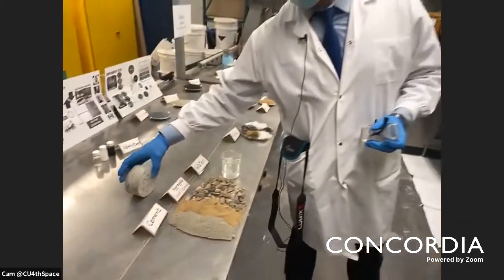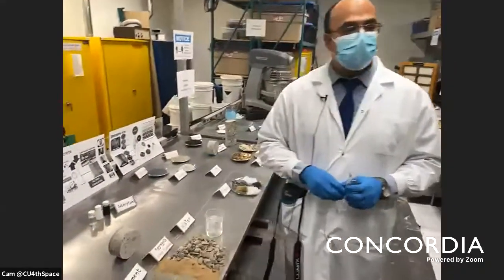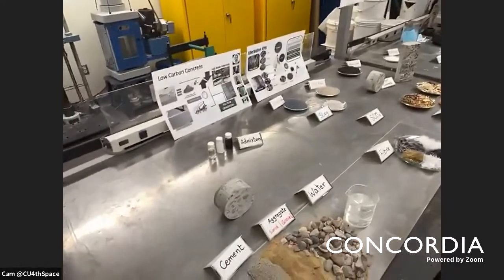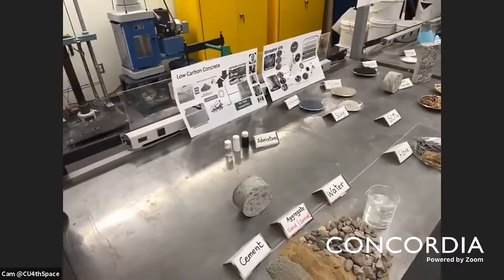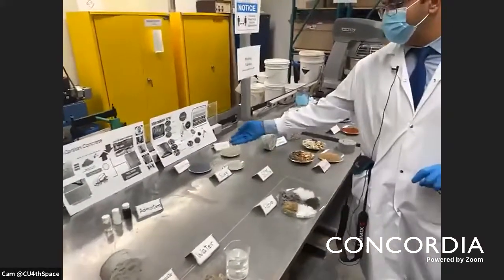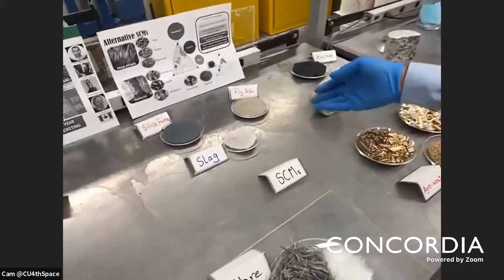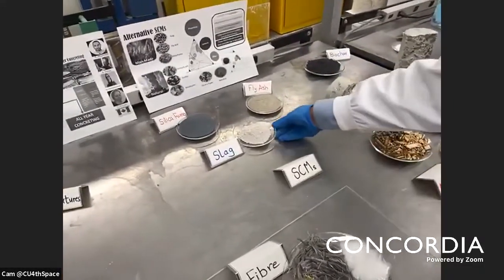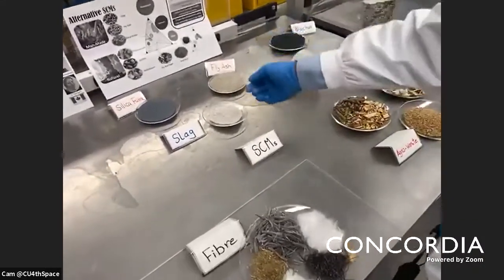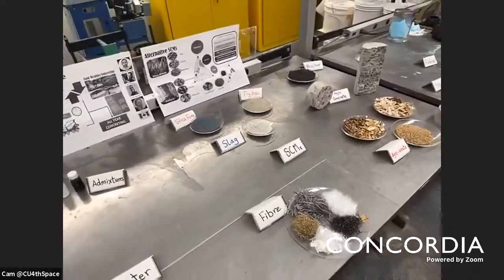If we would like to improve the properties of our concrete, we can use some kind of chemical admixtures. For example, this one will accelerate the strength gain, and increase freeze and thaw resistance for our concrete. Or we can add supplementary cementitious material types. These are actually industrial byproducts. For example, we have the slag coming out from iron production, we have fly ash, we have silica fume, and we have other types which can be natural, like volcanic ash.